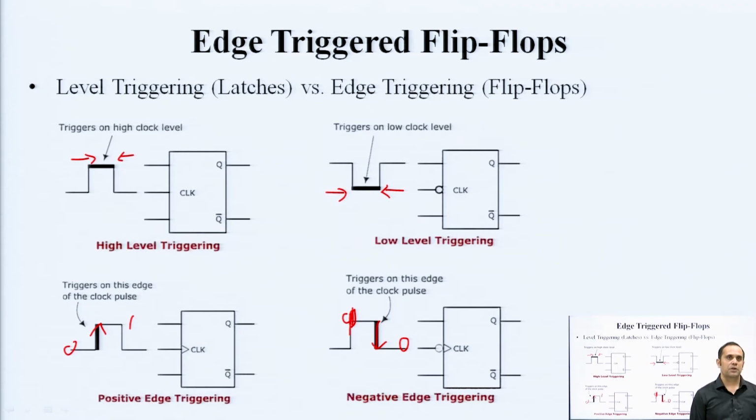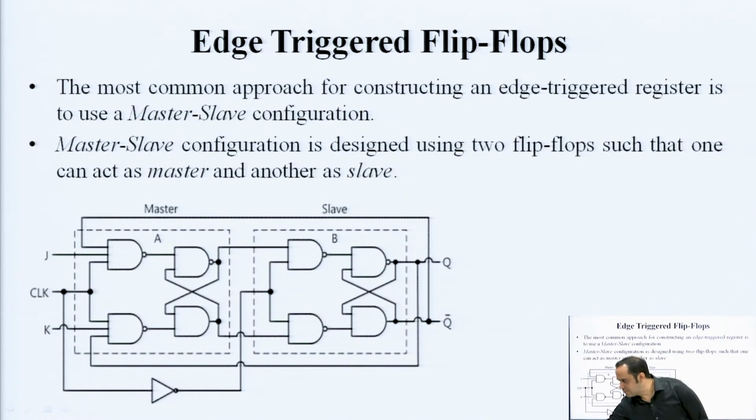Each flip flop can store 1 bit of data. So, for n bits of storage you need n flip flops. They can be synchronized together in parallel in such a way that a single clock trigger, a single pulse at the clock or enable, can update the content of a large number of n flip flops. This is a major difference between a latch and a flip flop. Flip flops are the most basic storage element of any sequential circuit. So, let us proceed further.